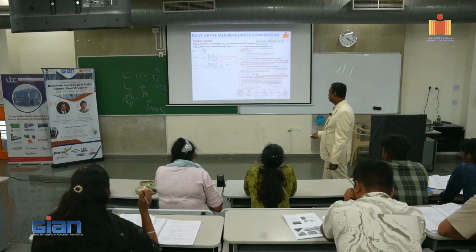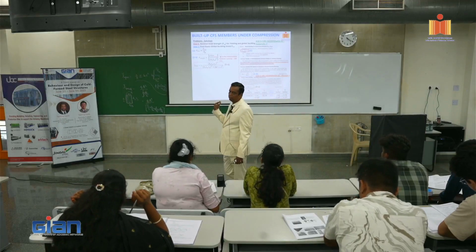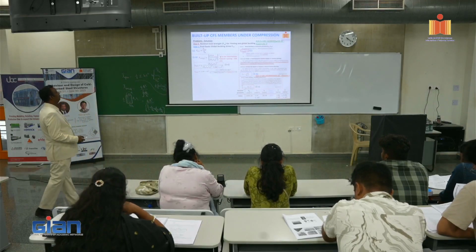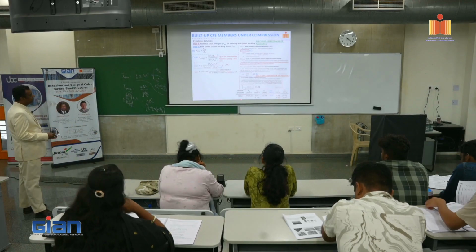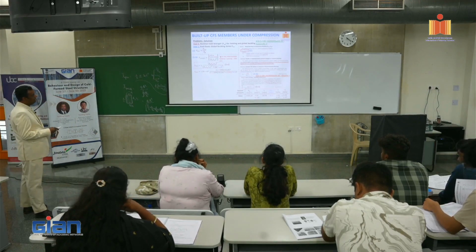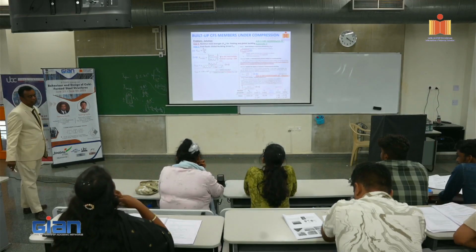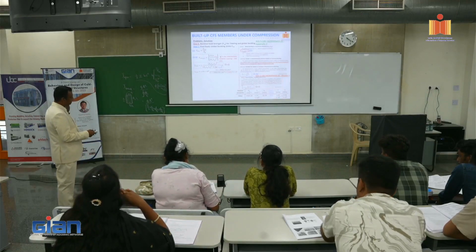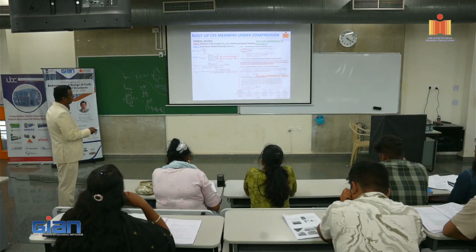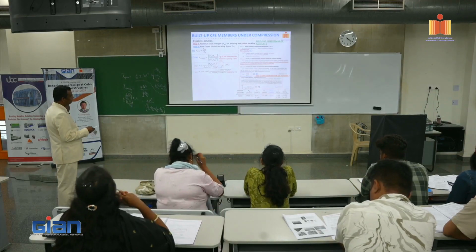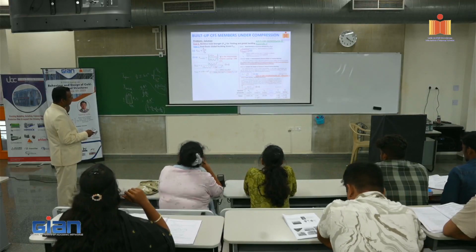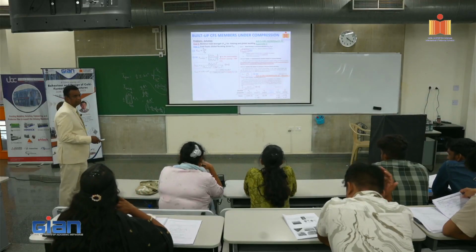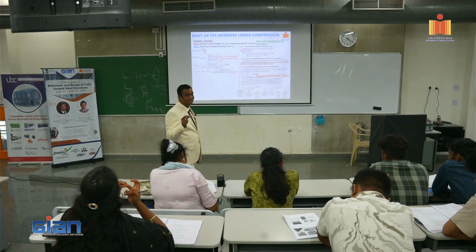So when we do so, A is the fastener spacing here. In the problem, we know that it is 300 mm, correct? So now we have this IY is 1.59 into 10 power 6, right, into 1 into 1800, because here the nogging is there, so it has a double curvature, sinusoidal curve. So you have 1800 as the spacing, and RY is 33.28, which is already given here. This is for the combined cross section. Similarly, the same thing, plus the spacing is 300 divided by 26.3. This is for RIY, which is for the individual cross section. You have to put that RIY. Am I clear?